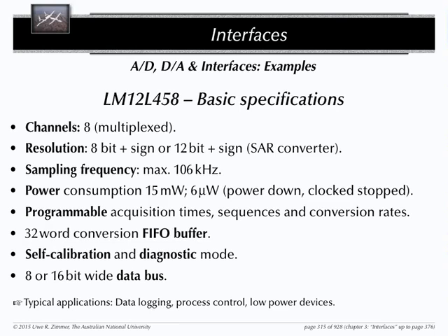No, you have to actively program this device to go into a sleep mode. It doesn't automatically go into sleep mode. The chip select is only for the communication on the memory bus. The chip select itself has nothing to do with the power down mode.